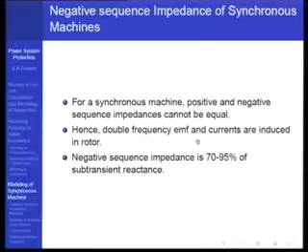Now if you look at the negative sequence data, what happens when the negative sequence flux is there in the stator is that the rotor is not latched on with that rotating flux. The negative sequence flux is rotating in the opposite direction, the rotor is going in another direction, so there is a double frequency rotation which is actually seen by the rotor, not at all a relatively static condition, which means that the induced EMFs will come in the rotor and they will create currents to oppose that particular flux or the rate of change of flux as per Lenz's law, which means that the net flux will tend to reduce.